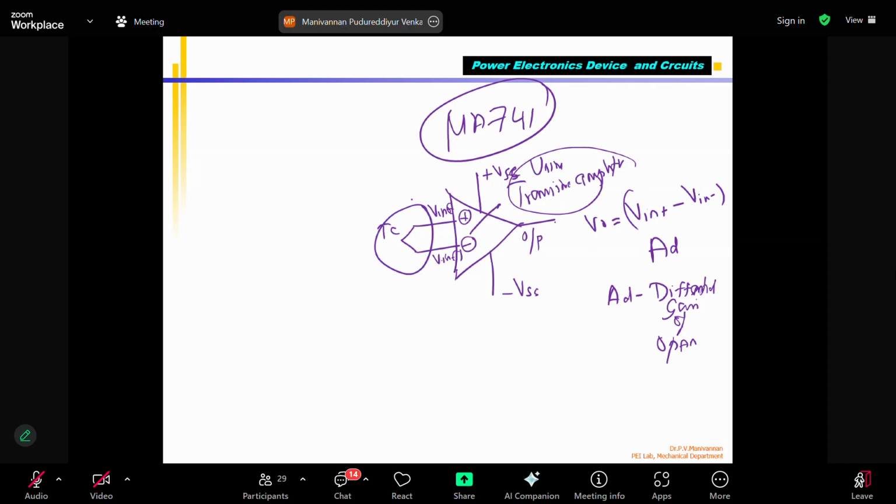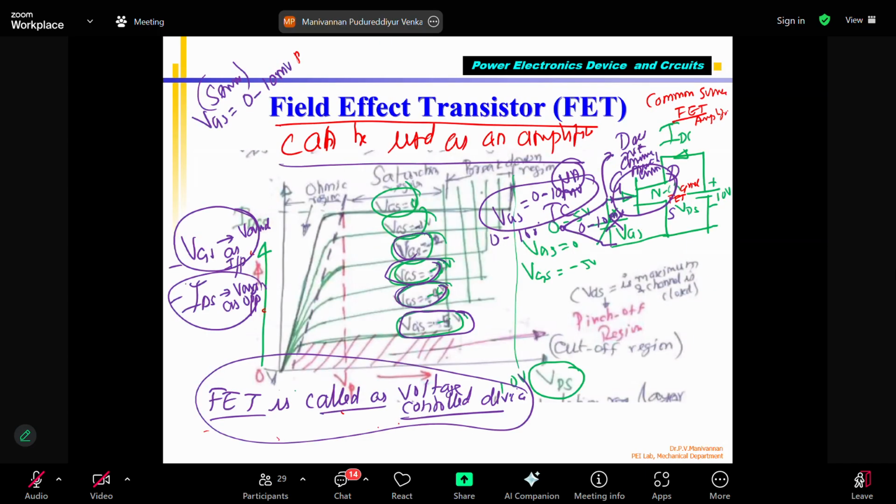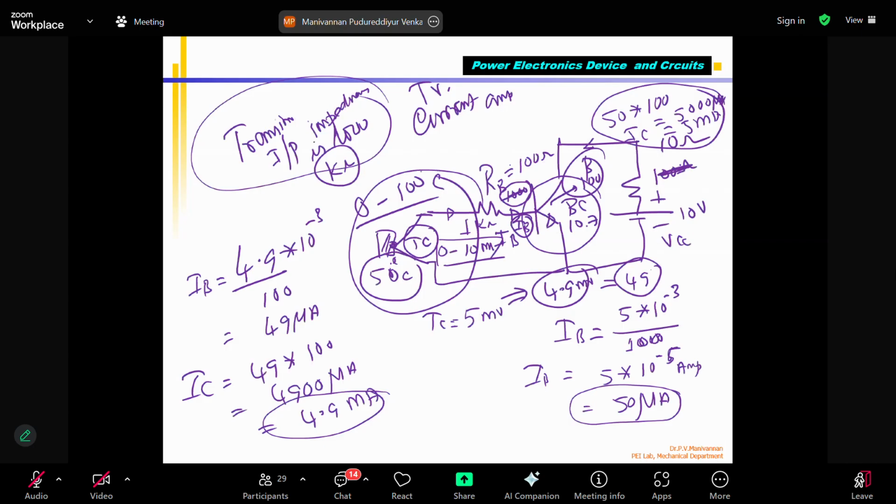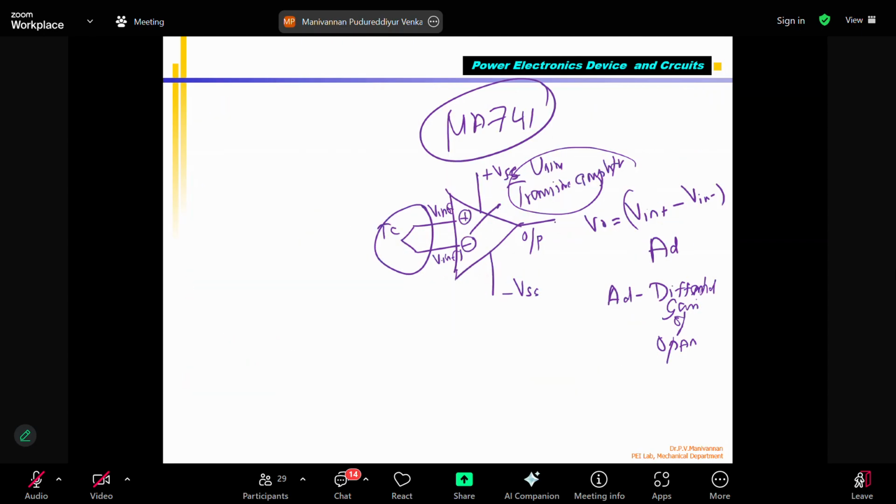We saw the single transistor, the common emitter transistor. Where is that? I deleted it. Yeah, if I use a single stage transistor amplifier, it will consume some current from the sensor. There can be error, because when I connect the amplifier, it takes current. So there is a measurement error. They call it the loading effect. To avoid that only, I told you they developed what you call the op-amp.